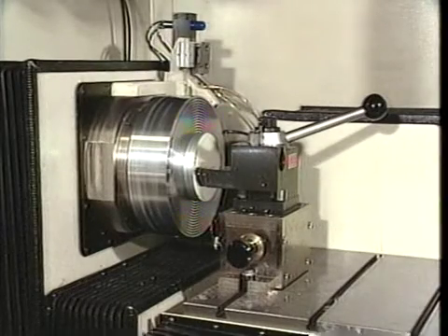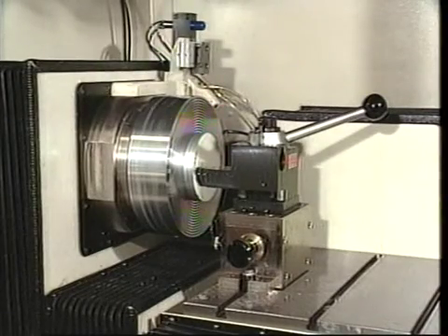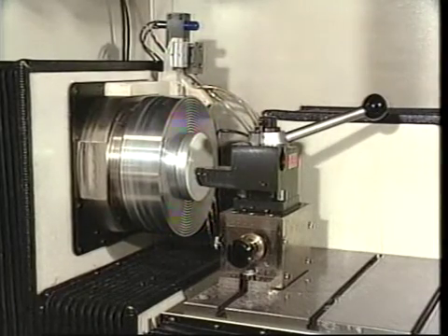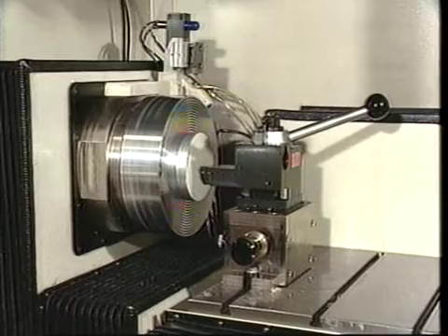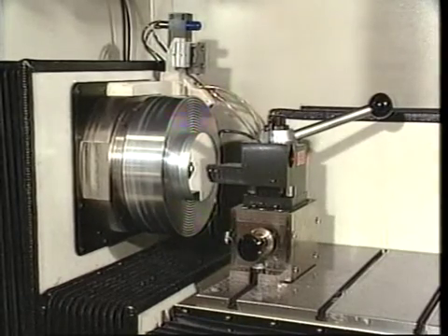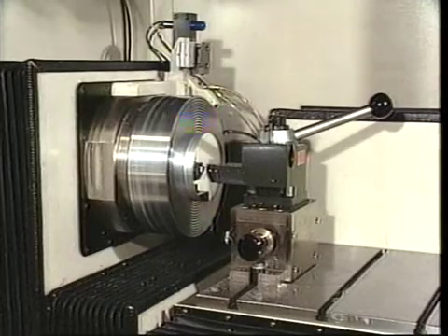Straightness errors for these diamond turning machines, or DTMs, are typically less than 1 micrometer over 25 millimeters of carriage travel. Since this motion error is not sufficiently greater than the 45 nanometers of straight edge error, the straight edge error cannot be ignored.